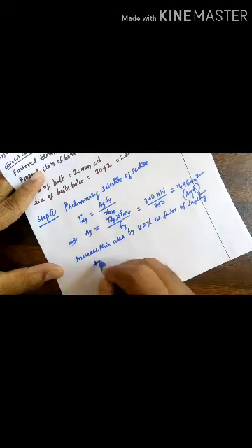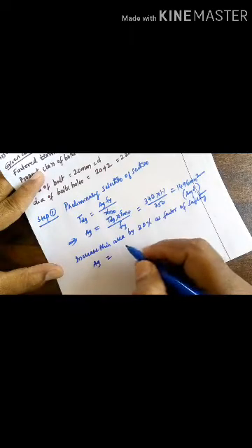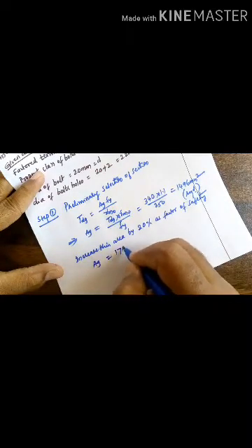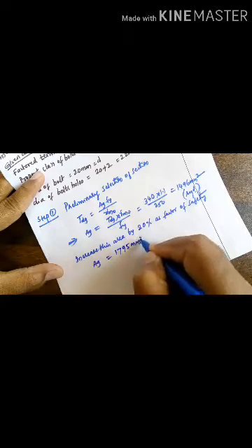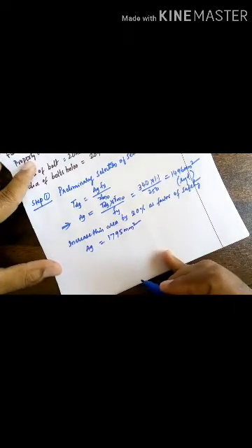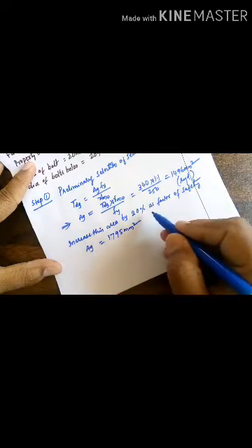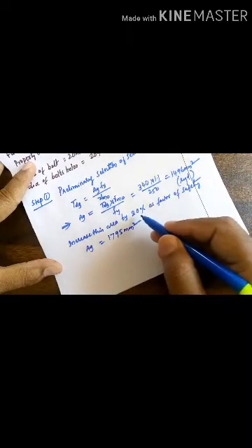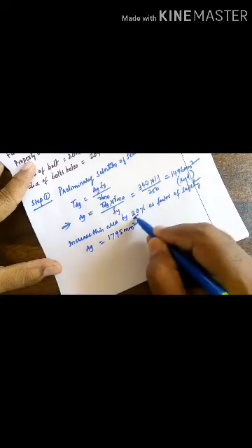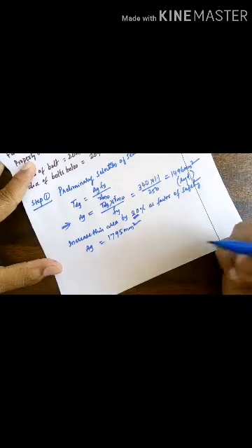After increasing the area you will get 1795 millimeter square. You increase the area by 20% as a factor of safety, or you may increase the area by 25%, as I mentioned in the procedure, 25 to 40%. So let us take a 20% increase in area here.